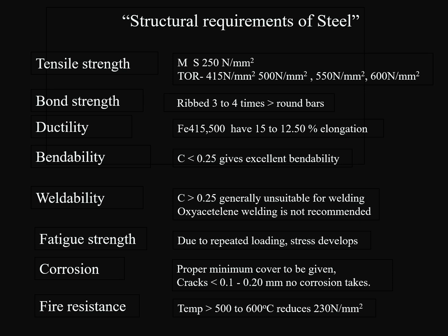Bendability. If the carbon content is less than 0.25, it gives excellent bendability. Weldability. If carbon content is more than 0.25, it is generally unsuitable for welding, especially oxyacetylene welding, which is not recommended. Fatigue strength. Due to repeated loading, stress develops, so the steel should be strong enough to sustain that stress.